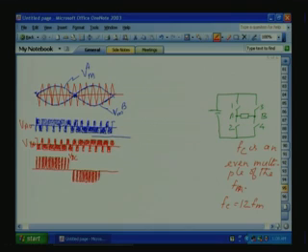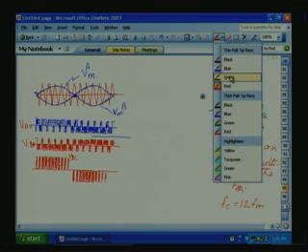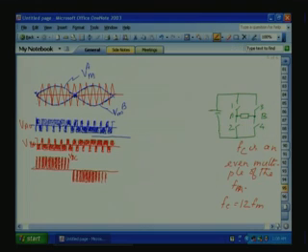At the same time, we have used 12 times the modulating frequency for the carrier wave. So here the fundamental will be like this. Now the fundamental gets added, but what about the carrier frequency at FC?